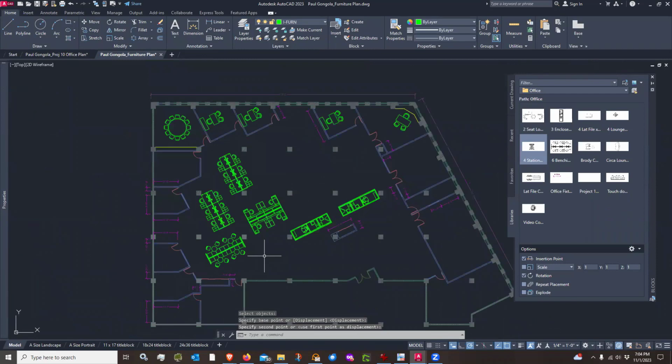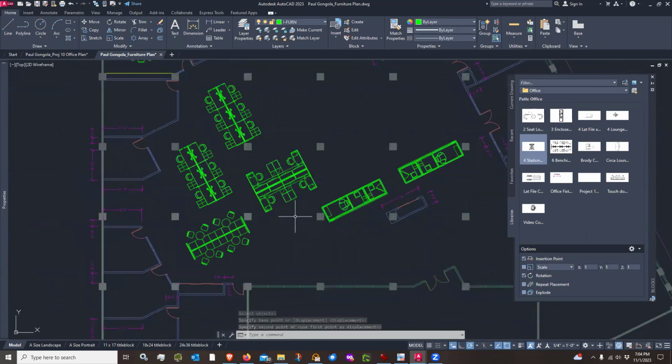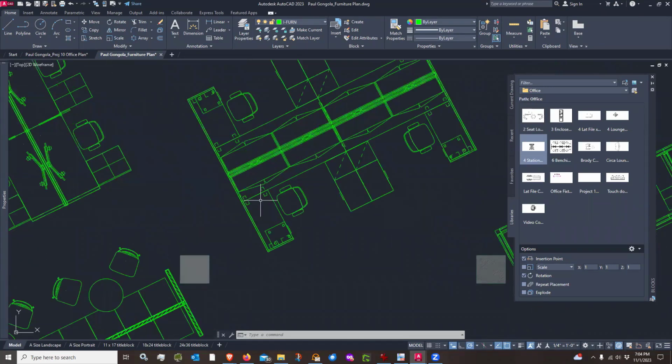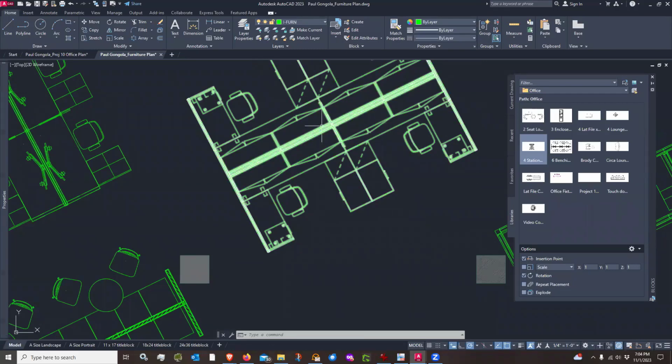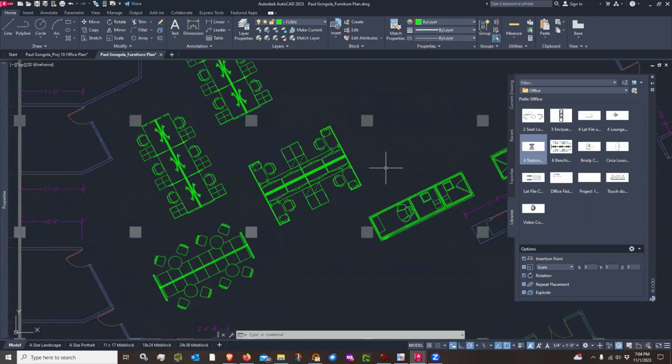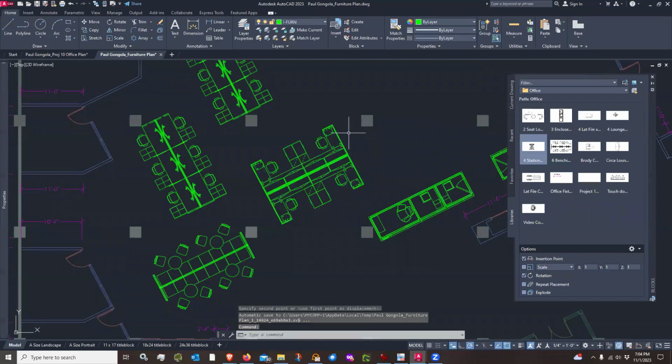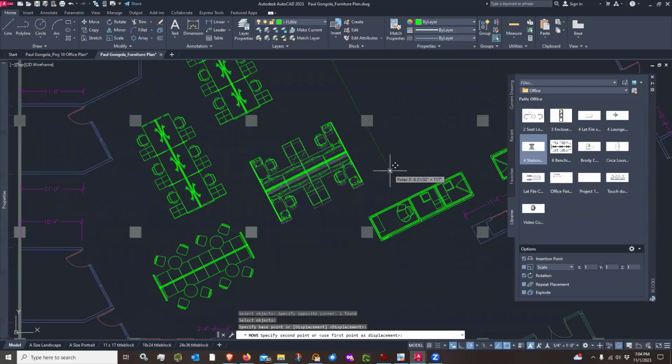So this is an instance where they're going to have to go downstairs to the tenant below, go in after hours, take the ceilings down, bring power in, drill a hole through their ceiling up into our floor, and then someplace bring in power that will whip into the spine here to bring them power. So what I'm trying to do here is visually get everything equal. So this is equal to that, and this is equal more or less to that. So I'm just kind of doing this visually.